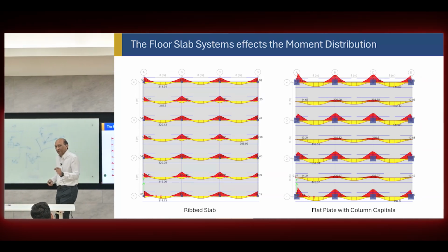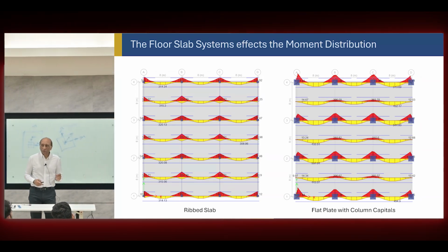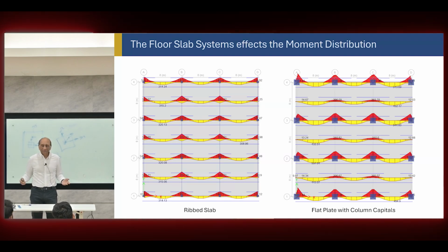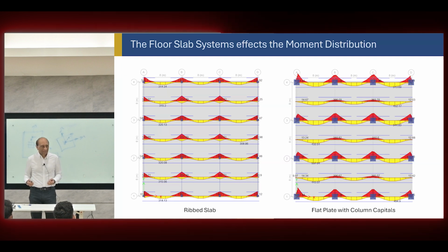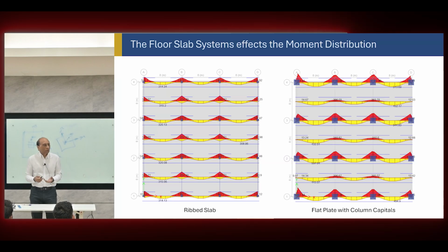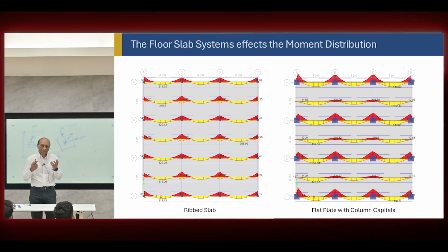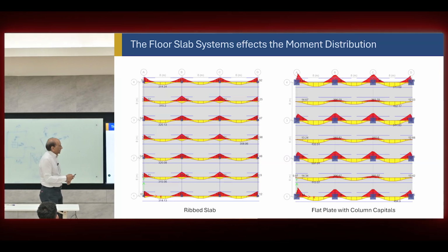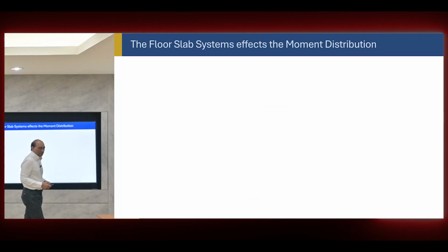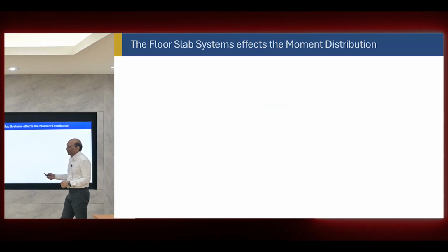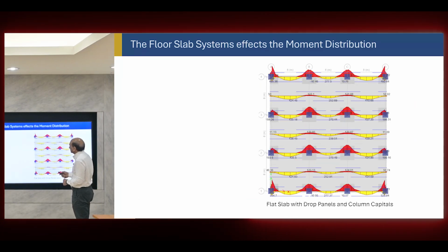In fact, it's the same for reinforced concrete and post-tension. There is also no difference. You just put post-tensioning in those strips and you're done. Because post-tensioning is nothing more than a reverse load. So post-tensioning, I'll talk about in a minute, is nothing more than a reverse load that you apply on the slab to lift up the slab, a load in a negative direction. You subtract that load and you're done. So it's as simple as that. In concept, of course. In practice, of course, we still have to do many calculations. Okay? But the concept is very clean.